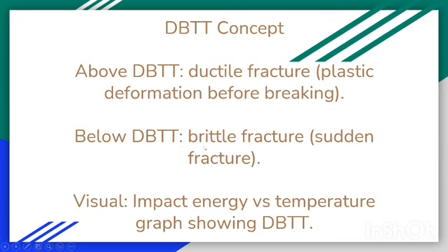This occurs only in BCC crystal structures, not in FCC crystal structures, because BCC has a limited number of independent slip systems. It only occurs in BCC crystals, not in FCC crystals. Due to this phenomenon, many machines and many vehicles are damaged, and everything gets damaged.